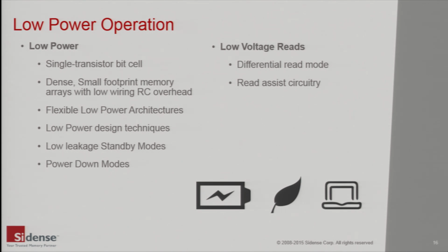Fundamental to low-power design is the fact that the Sidense antifuse bit cell does not consume DC current in a steady state, except for minimal leakage. However, as we have seen, there's more to the OTP than just a bit cell. The OTP power consumption of its supporting circuitry, its sense amps, multiplexers, decoders, interface circuits, etc., also needs to be considered.